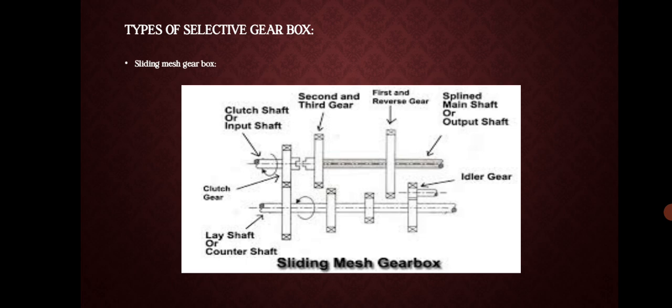Gear shift rails and forks are used to shift gears from one position to another. The shift rails are kept in position with the help of spring-loaded detent balls or by other devices. This allows one pair of gears to engage at one time, otherwise the transmission system will not function and damage may occur to some of the components. The shafts are mounted in the transmission housing on bearings.